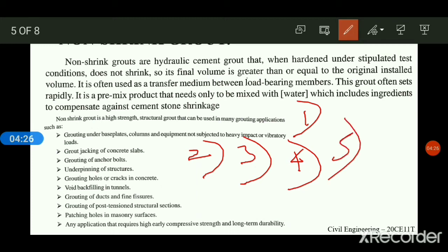And next, for aggregates: I'm talking about the composition of grouting materials, that is cementing materials, early strength components, water reducing components, water retention components. And fifth one is aggregate. River sand, mountain sand, machine sand can be used. And last, for intumescent components: gypsum, calcium sulfoaluminate, calcium oxide. These are the components used for the composition of grouting material.